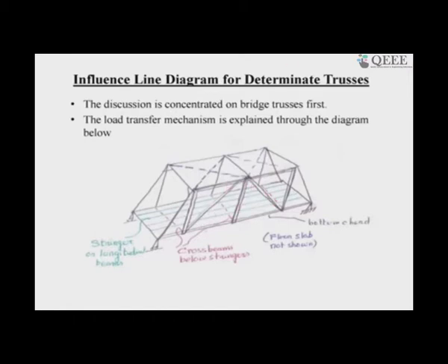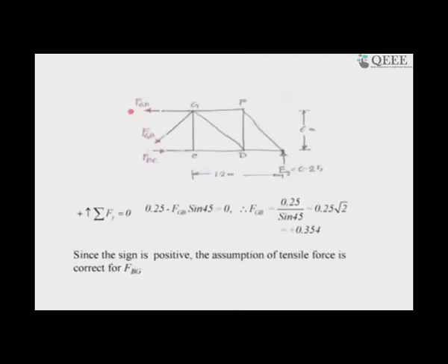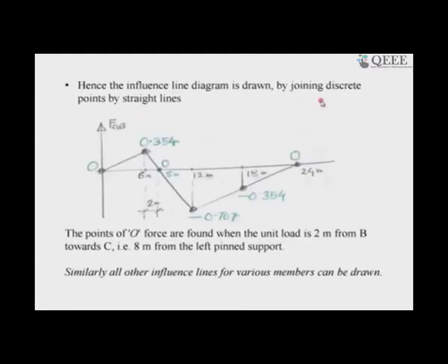Now, next, yes, so it is basically a truss solution with unit load at different joints, and the load moves on the bottom chord, and that is one of the examples for the truss. Yes, please. I think there is nothing basic, but we have solved probably one problem. Yeah, this is the shape of the influence line diagram for the truss, and we have also shown that the Mueller-Breslau principle is equally applicable for trusses.